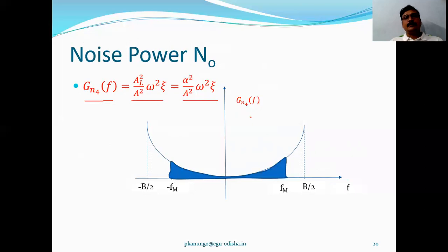This frequency power spectral density is a plot of frequency versus the power. So this is the power spectral density. You look at here, this is the parabolic surface. This is the power spectral density of, you can say, the input noise to the baseband filter, or the output of the diode detector or envelope detector.